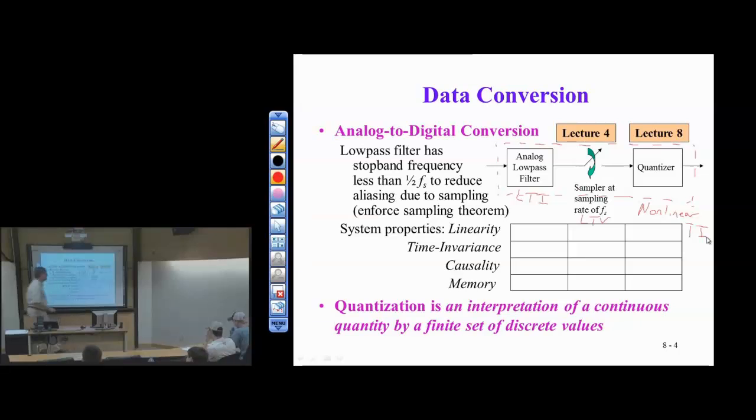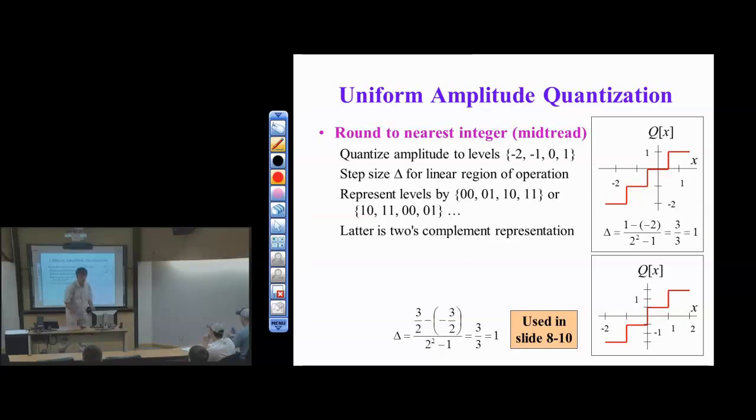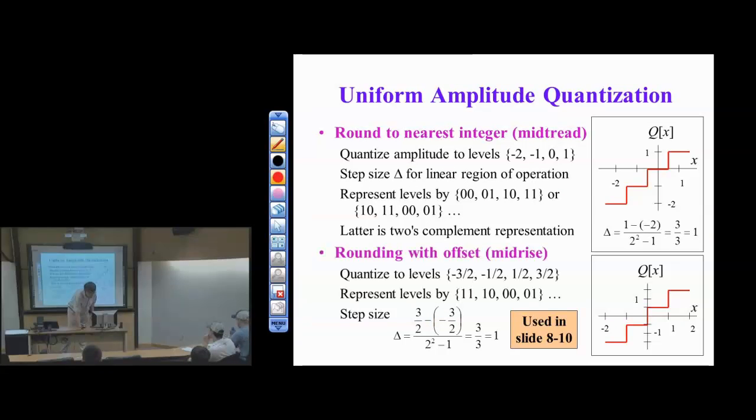So we can, and we do, and we have. We've looked at sampling in a lot of different contexts, filtering. So today we're going to dive into the quantizer a little bit more deeply. So we've done a few introductory slides on the quantizer. And the key takeaway today is to derive the signal-to-noise ratio at the output of the quantizer, which we'll see will be 6 dB per bit of quantization plus an offset. It's a very important formula. You'll use that one, I think, the rest of your career, dealing with any quantized data of any kind in any application scenario. So it's a very generic result.